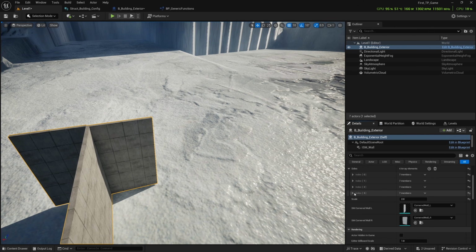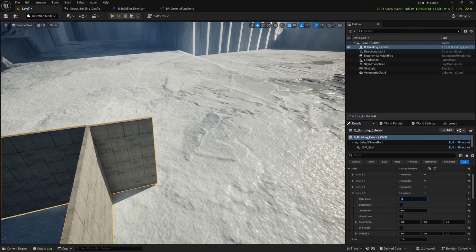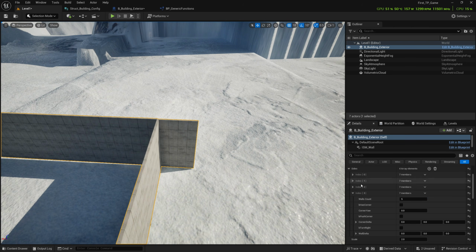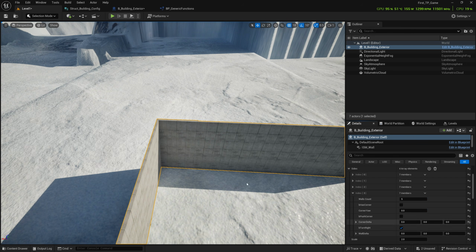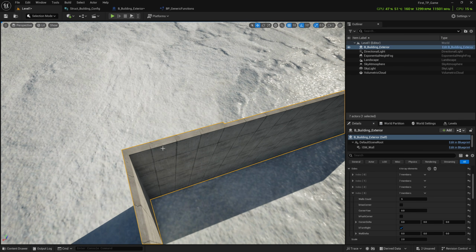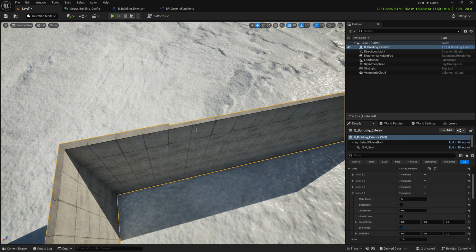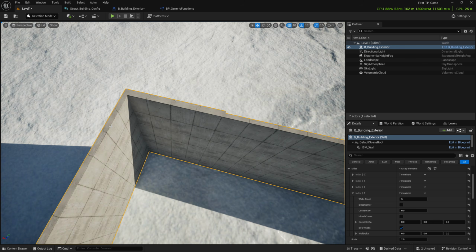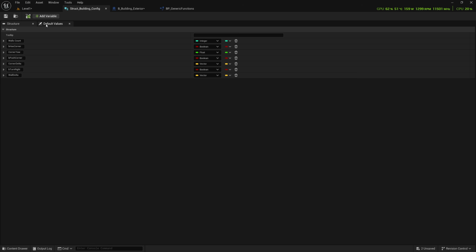You can add one more, add 5 walls, and this time it should be turned right. So turn right, and you see now this wall is overlapping. Why is it happening? Because you said 5 walls, but one wall is already completed by this cornered wall. So we have to make a parameter that allows you to push the walls further because one wall is completed by this corner. So we'll go back, we'll say b push wall, save, change this to